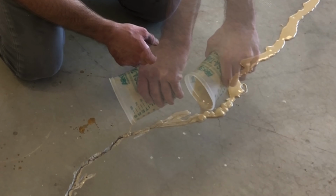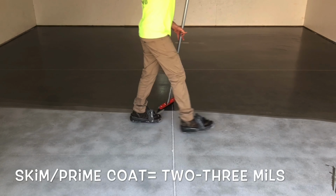Where this will, it's designed for a multitude of applications. In many cases, it's overkill, but that's the advantage of having something that can allow you to do a larger magnitude of repairs and still turn it around quickly, accept traffic and other coatings on top of it. But you could certainly use, depending on the time available, a concrete repair material or a patch, as long as it's appropriate for the type of system going over it, and other resinous coatings, epoxies, things like that. So you do have options, but the biggest thing is making sure that the product you're using is acceptable for the depth and what is going to go back on top of it.